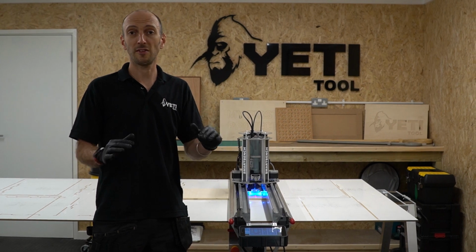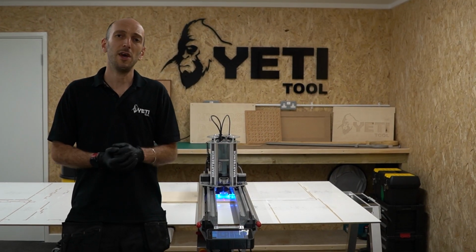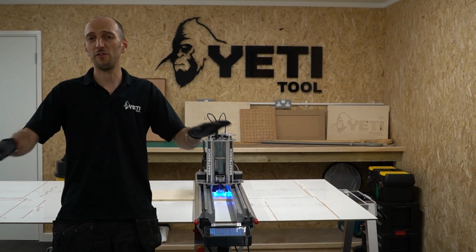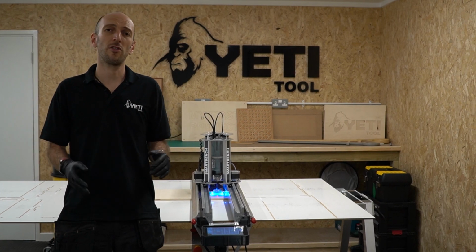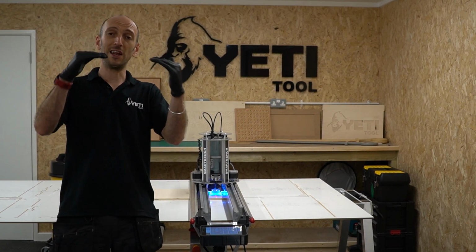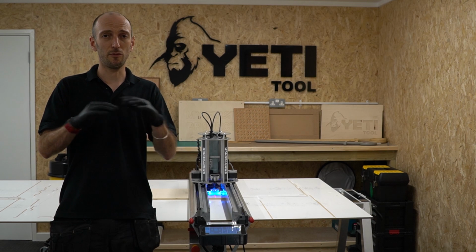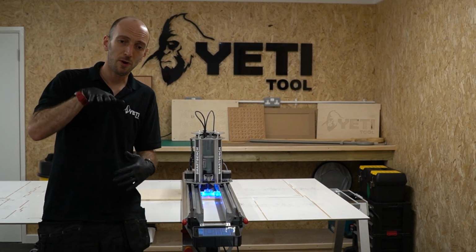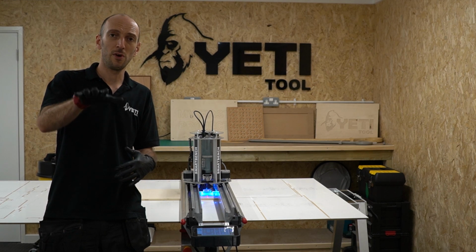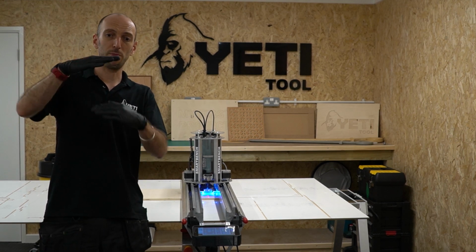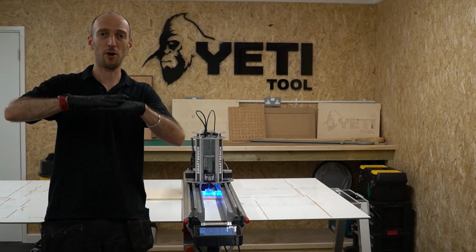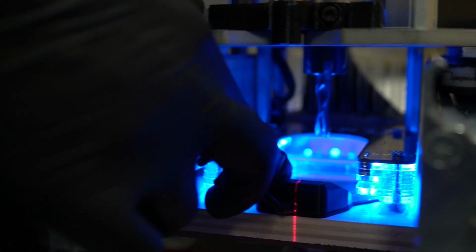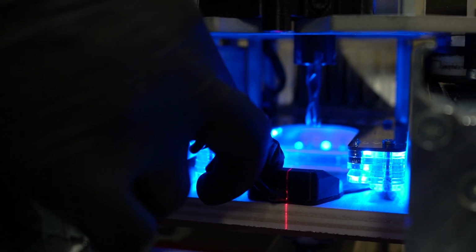And the second thing is to make sure that the area is void of any chips or dust that might artificially lift that Pro plate and give a wrong Z height. Similarly, make sure when you're pushing the Pro plate underneath the dust shoe, give an amount of pressure which will make sure that it's sitting flatly on the top surface of the material and not giving an artificially high reading.